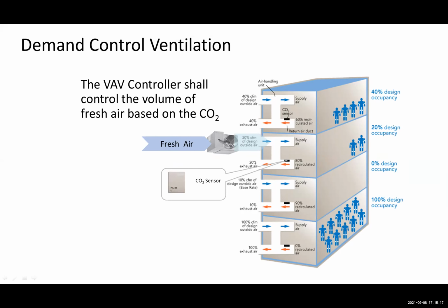So how is that possible with demand control ventilation? We have to have things designed as per ASHRAE and ventilation standards, local conditions and codes. So we need to ensure that based on the occupancy, the variable air volume system's controls component delivers the amount of fresh air which is required, because fresh air contributes a sizable amount of cooling and heating load to the equipment we are talking about.